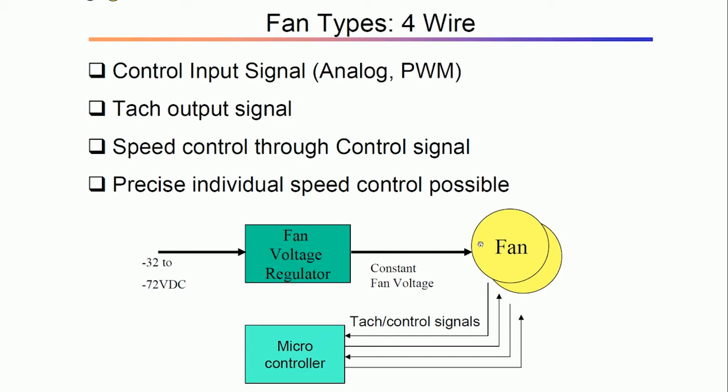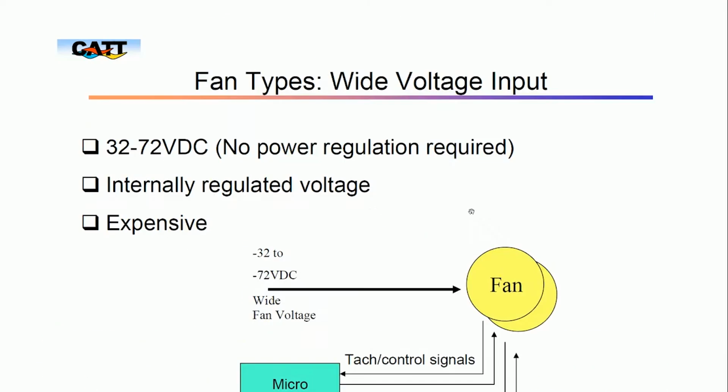4 wires. It is used normally in electronics whenever you want to take a measurement of even a resistor, to prevent the leads from affecting that, you have leads directly at that point. So, instead of taking something here, you need to take, for everything you end up with 2 leads. So, if you have a full 4 wire system like this, you have much better control.